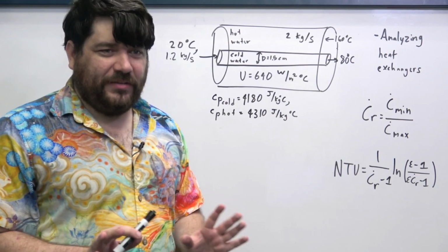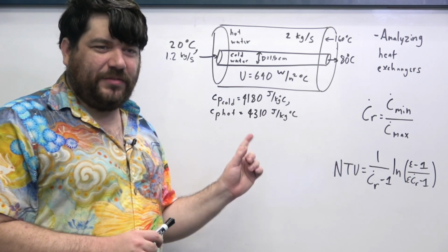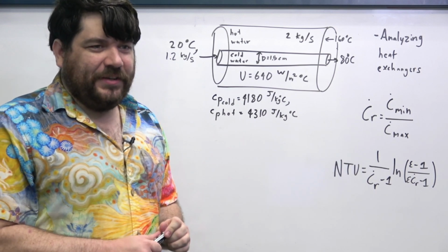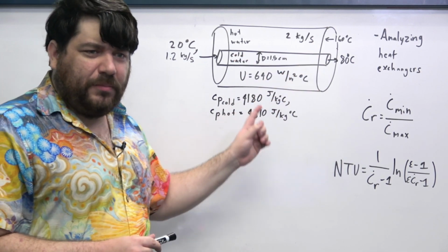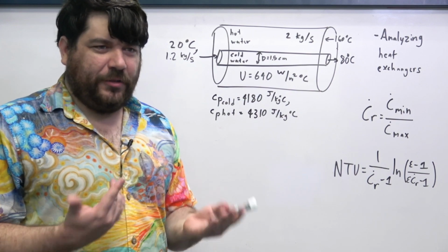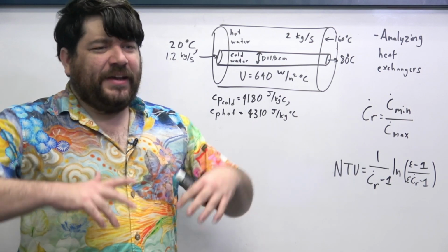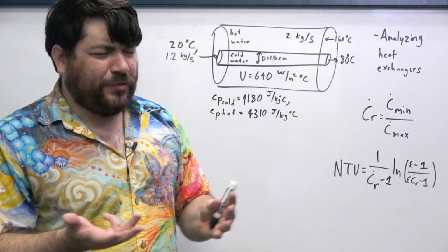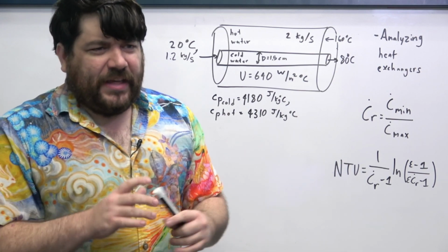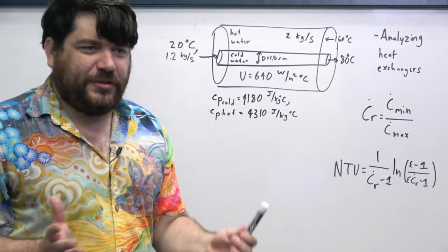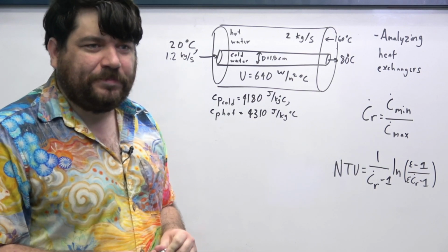Be aware, we're being a little bit sloppy with this because there isn't just a single specific heat capacity. That specific heat capacity for either the hot or cold liquid is going to change as the temperature of the liquid changes through the heat exchanger. But these are approximately representative values at either average temperatures or the temperature that we have available to us for those liquids in this problem. And we assume that the error that is associated with our calculations based off of this assumption is either negligible or factored in to the certainty that we have for whatever it is that we're calculating.